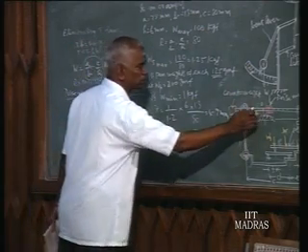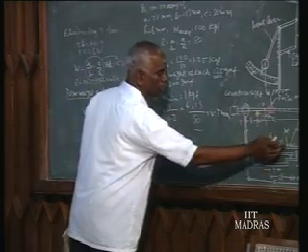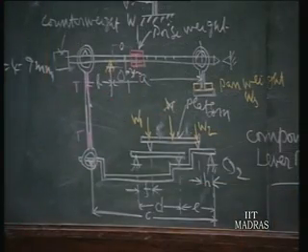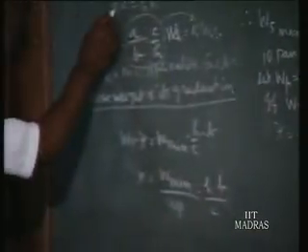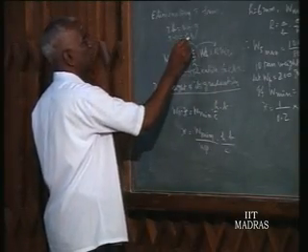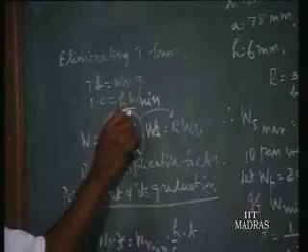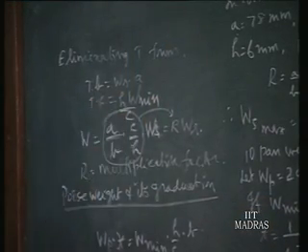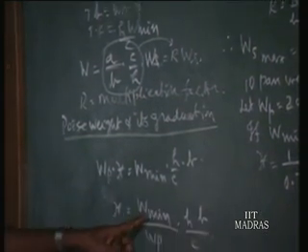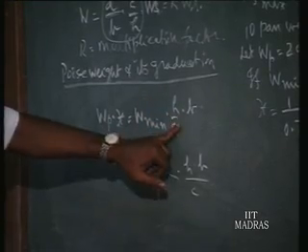That is being balanced on this side of the pivot. The other side comes from the 1 kilogram weight here, that we call W minimum. So the tension on the tie rod will be W minimum into H by C. This, into B, will give the moment about O. So W minimum H by C into B will be the moment on the other side. We equate these two moments.